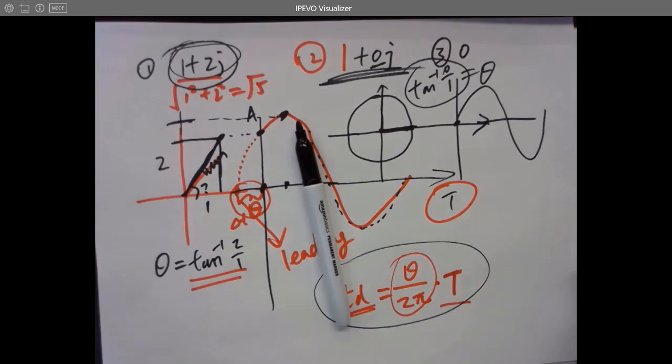Use an A to D converter, analog to digital converter. You can buy a little chip which can do the A to D conversion, or Arduino has a 10-bit ADC inside the chip, so you can directly convert temperature analog data into a digital signal. If you need a higher resolution AD converter, you can buy a better one from Microchip. All the MCP series, I forget the versions, can reach up to around 14-bit resolution.